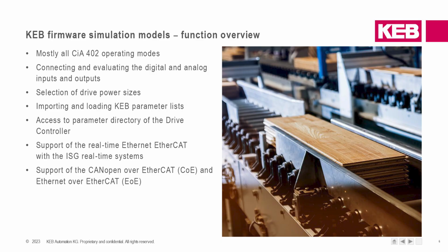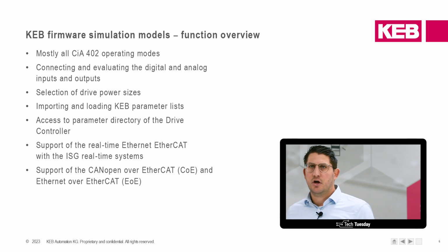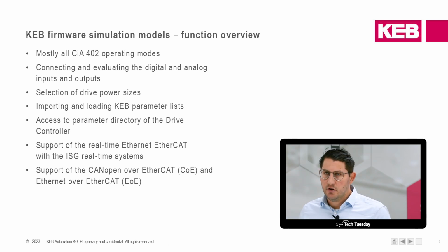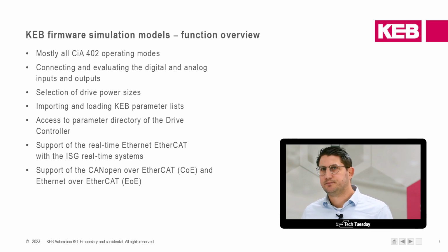The function overview of our simulation model is very big. Almost all of our CiA 402 operating modes are implemented in our simulation models. The connecting and evaluating of digital inputs and outputs is given. The selection of the KEB drive power size is also given in the engineering environment of your simulation environment. The import and loading function of our KEB parameter lists is also given with these simulation models.